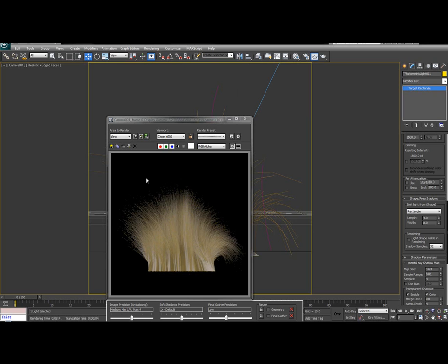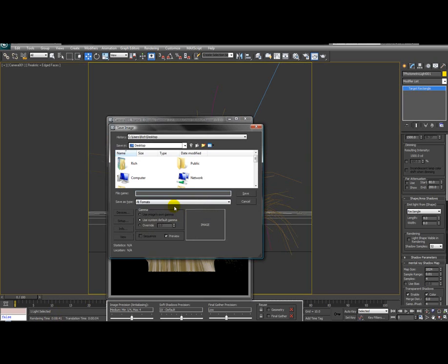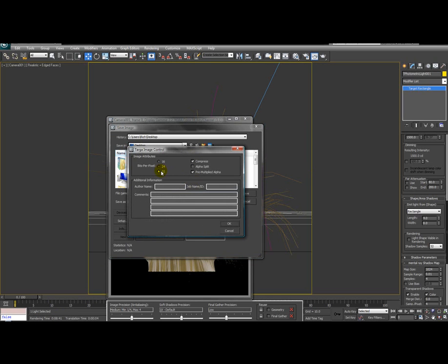So this is the result. After 9 minutes, or 8 minutes and 41 seconds, here's the result that we got. I can now just save this, and I want to make sure that I save this as a format that has an alpha channel. So I'll save this off as a targa, and just call this Ray Hair Test 2. And make sure that I do save it as 32 bits per pixel, and pre-multiplied alpha is checked.